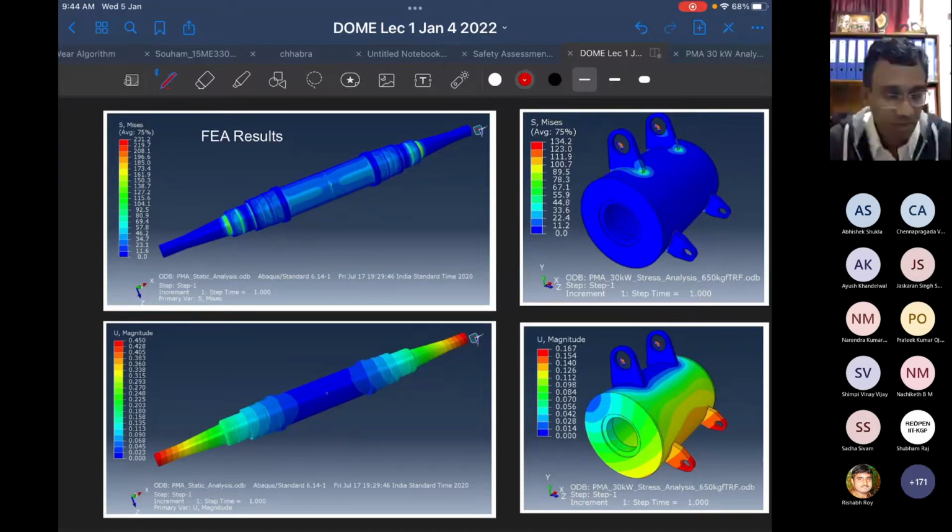If you have over designed, you have to thin the components to make sure that you have the right safety factor without things being too overweight. If some stresses are too high in some particular region, then you need to think of ways to reduce them. So this is it really.